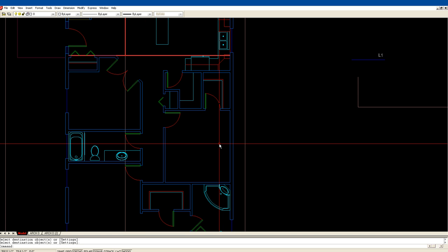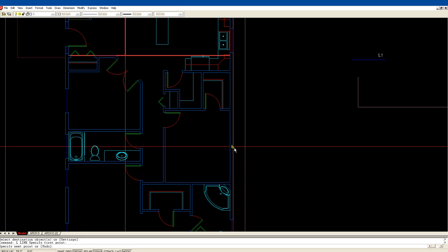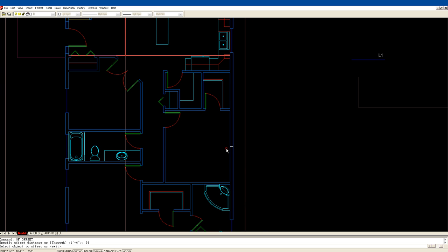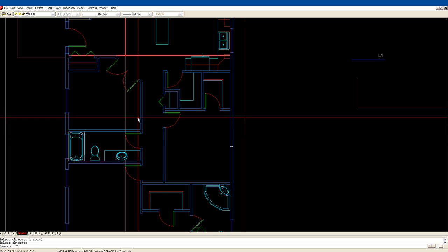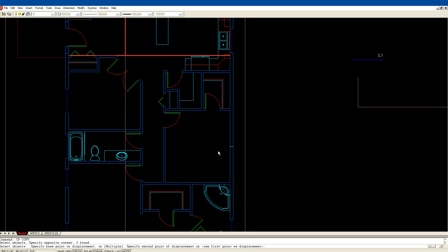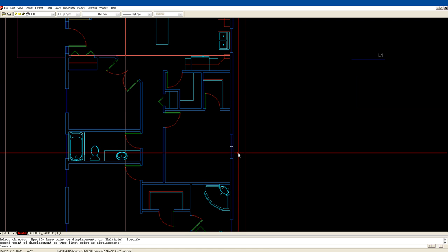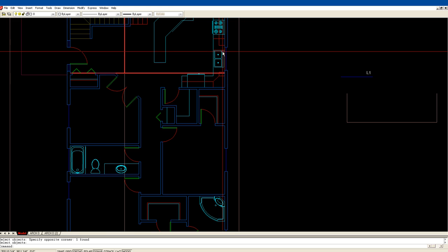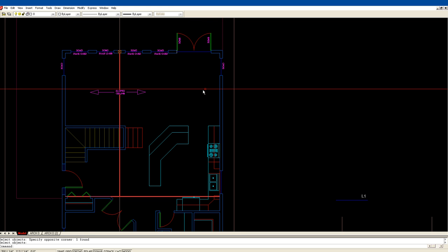Okay, this window, basically it's a bedroom, and so I'm going to make a 4 foot by 3 foot. So I'm going to offset 24. You know what? We can do something else here. We can just copy this 4 by 3 from the center there, and put it right on the center there, and then trim. And erase. Okay, that takes care of that window. We've already got that one, and that's it for now.